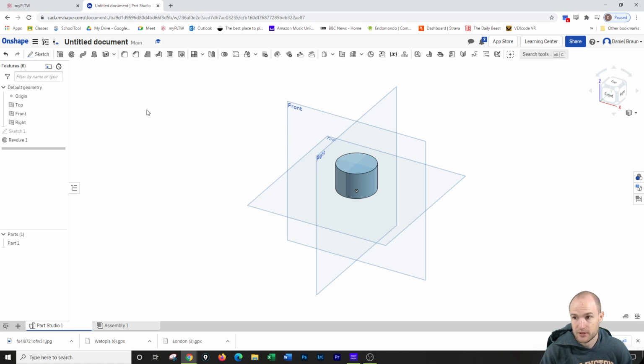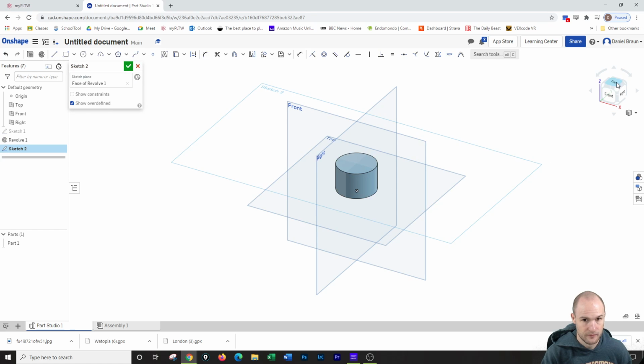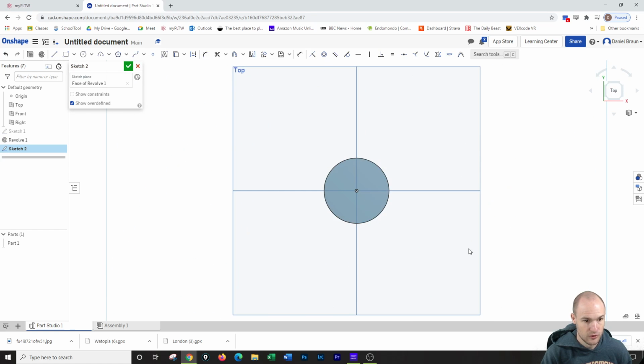So the next step is the top portion, which is going to go in 2 steps. So I'm going to see if I can do this way. I'm going to do a sketch on top. There is definitely a midpoint of this object, and since I started it on the center, it's going to be easier. So I'm going to do a rectangle with a center point.